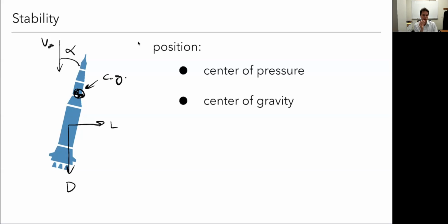So we generally don't worry about that distinction because the center of pressure, yes, in principle, it does move around, but because we stay right by 0, it's hardly moving at all. So most commonly, you'll hear people say for stability that the center of gravity needs to be above the center of pressure. But if we're being more careful, it's really the aerodynamic center that matters. It's just that it doesn't move very much for a rocket. So that's what you'll typically hear.